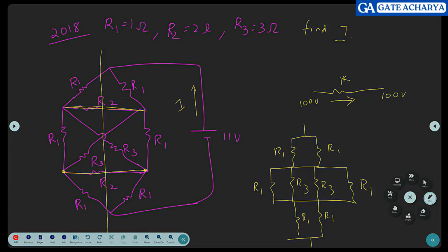So the point is, there are a class of circuits called bridge circuits, which is used primarily for measuring from low frequency to high frequency. And the idea is, if the circuit is symmetric, left side, right side, there is no potential difference developed at all. It's a balanced bridge. And so is this case, balanced bridge.